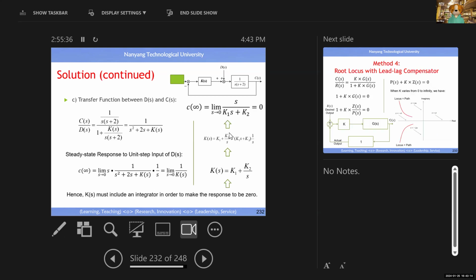Then for the second SISO, this is disturbances, whatever is produced by disturbances in this error, yes, right? So you look at the transfer function, okay, forward path divided by 1 minus loop, something like that. Then you look at the steady state output due to this guy, right? So when this guy is a unit step function, you see S times the transfer function. When this guy is unit step, 1 over S. Okay, simplifying, you get this one.